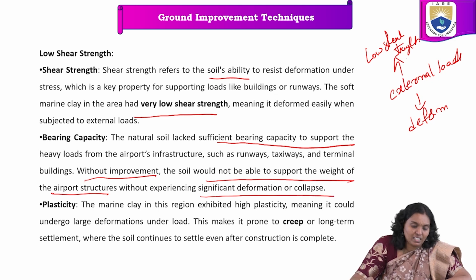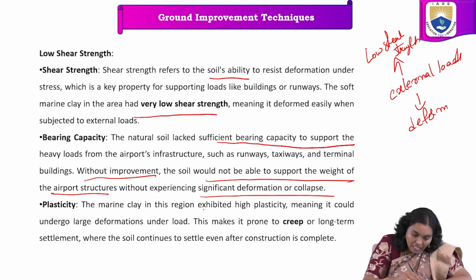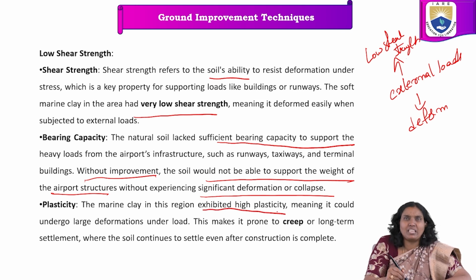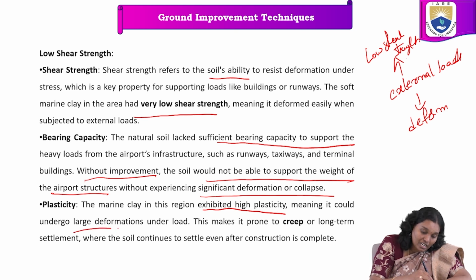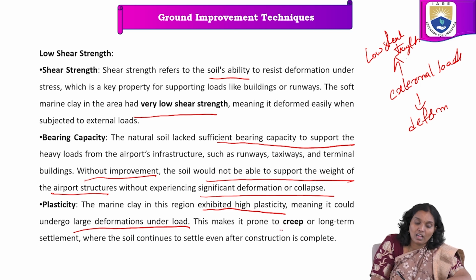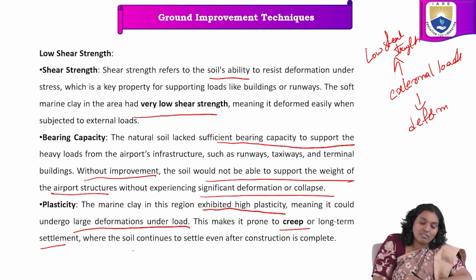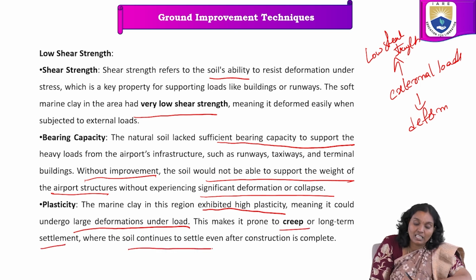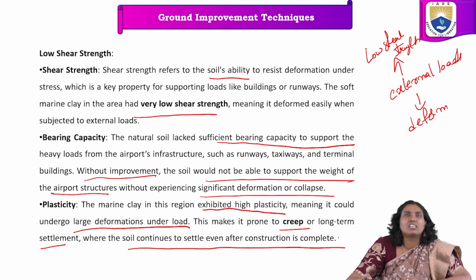In plasticity, the marine clay in this region exhibited high plasticity, meaning it could undergo large deformations under load. This makes it prone to creep or long-term settlement, where the soil continues to settle even after construction is complete.